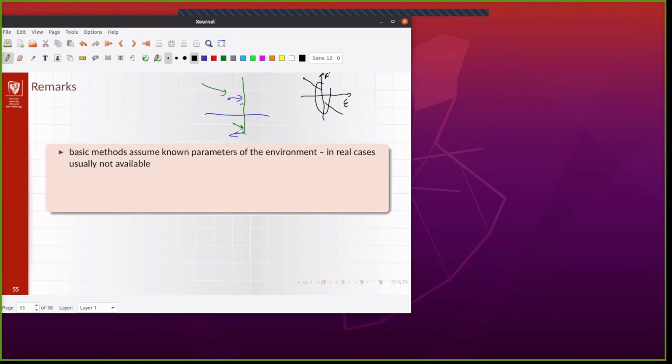There's also an approach that is sometimes used, where you have a third controller, an intermediate one, that is responsible for controlling the phase of passing from free space control to the contact point, just to avoid these chattering situations and unpredictable or unwanted movement at the contact point.